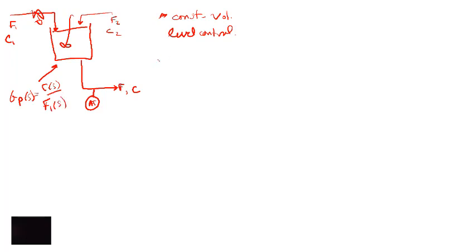We also know that F equals F1 plus F2, because of our constant volume assumption. So we're going to go ahead and derive the balance for this process first. We have to do a mole balance, so I have the derivative in the number of moles, dN/dt, equals... I'm going to use volume. I'm going to say the F's are in terms of volumetric flow rate.